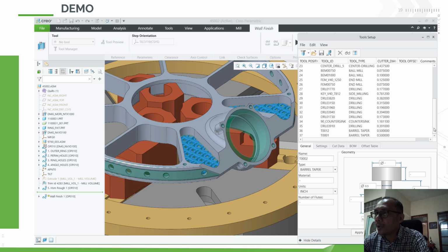Then I can go in and say, what walls do we want to machine? I want to grab those walls. And then I want to say, go to their surface, and then you will see there are lots of different parameters, methods of controlling it, and so forth. But you have a step depth, and then let's set a good feed rate.